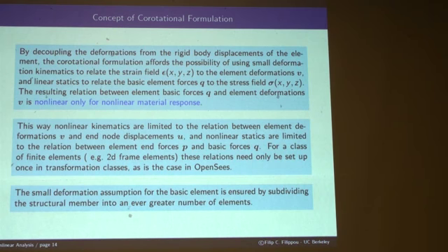And the same, of course, is true for the stress field sigma and its relation to the basic element forces Q. You see, just by relating Q to P and V to U, I haven't done anything more than solve a discrete problem. Now I have to go inside the element and see what strains are the ones caused by these V's. And by doing this treatment, I can afford to consider the strains small. Okay? That's a key idea.